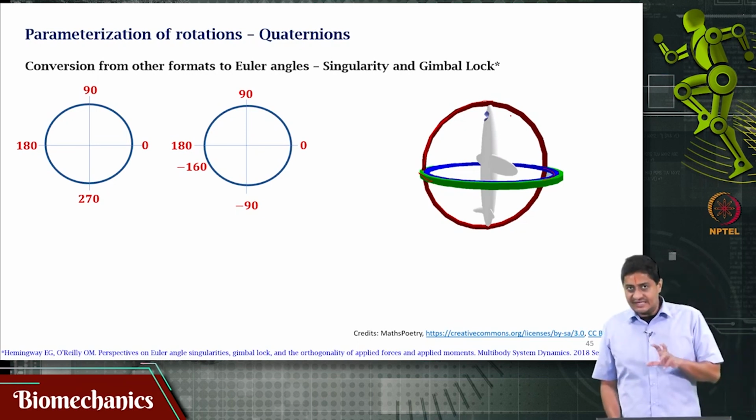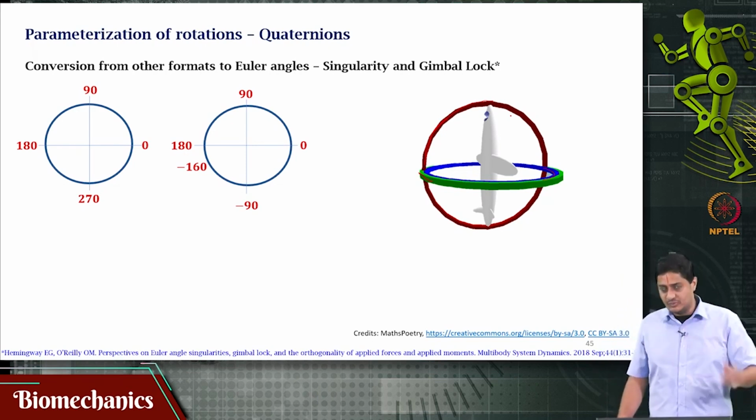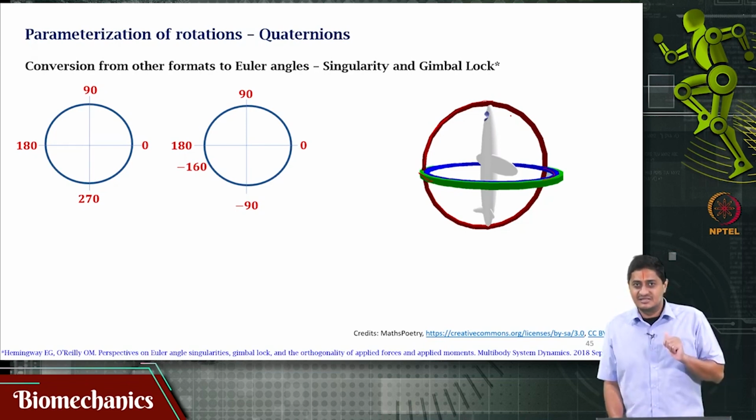Now, if the data from the blue gimbal reads as some value, that could be either because the blue gimbal itself is moving or because the green gimbal is moving. There is an uncertainty as to where this is coming from. It is not clear. So, this is the famous problem of gimbal lock or singularity.